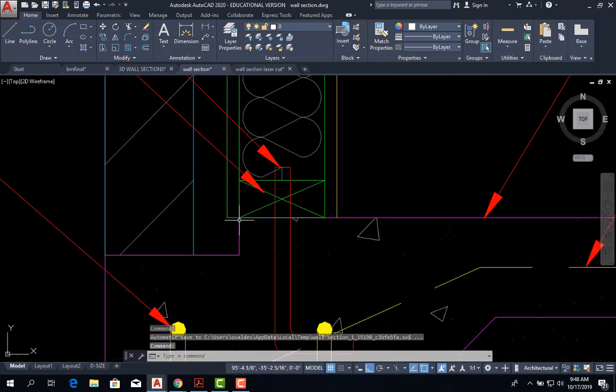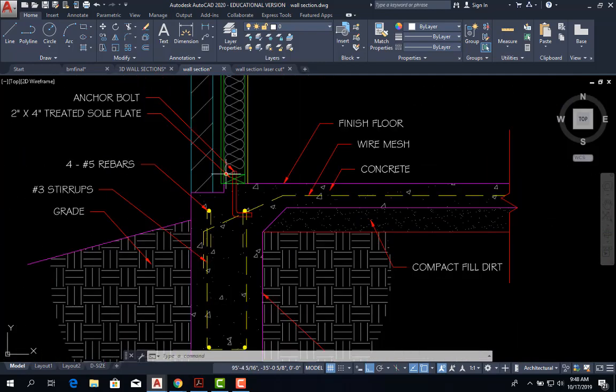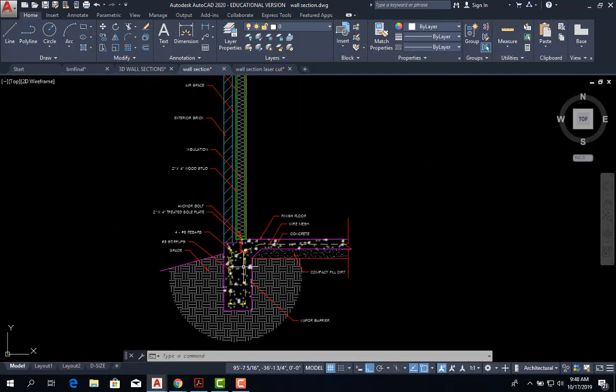Then this is the brick ledge, and we saw that too. The brick comes all the way down and sits here, and then the sheathing right here. You can have a flashing right here, and we saw that one in the house, and then this is the airspace. So you can have an idea of what we're seeing.